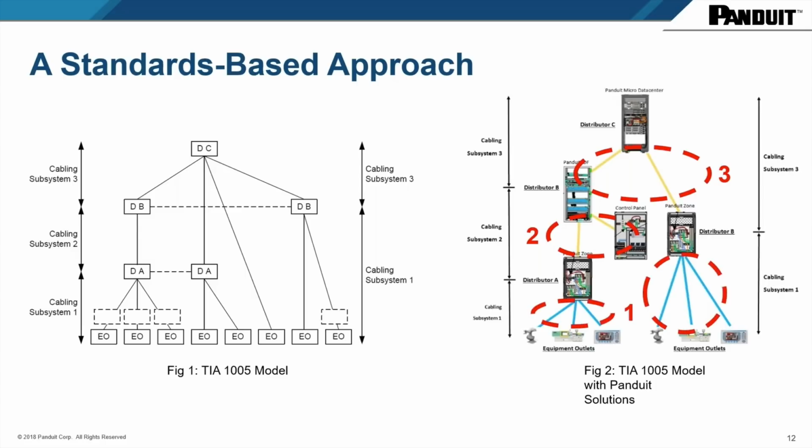Now, what we call the last mile in a network is where a zone controller is connected to the edge devices. All the cabling that's run between those systems is generally copper. So why do we run copper at the edge devices versus fiber? Copper connectivity is sturdier, and there are a lot of connectivity solutions that you find selling in the industry that are copper connections. You will not find many companies delivering fiber connectivity to the edge devices.